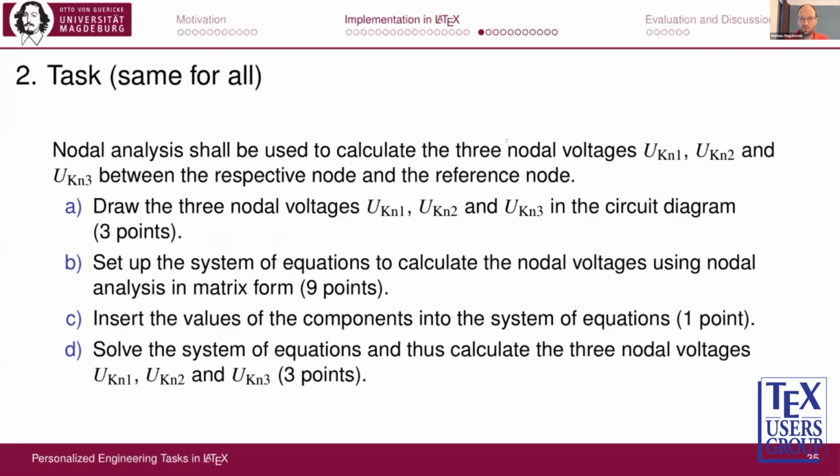These voltages are called nodal voltages, and symbols are already given here for them. So the task is that students should draw these nodal voltages in the given circuit diagram, set up an equation system to calculate these voltages, and solve the equation system after inserting the values of the components inside the system of equations.